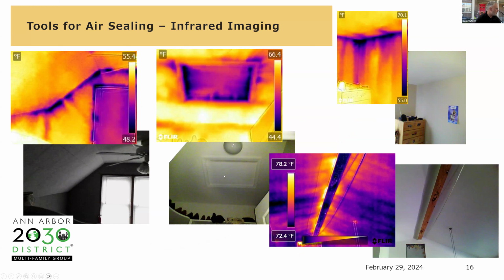We have air leakage at the attic hatch, so you can use a thin foam gasket, 3/8 of an inch, 1/4 inch gasket to seal that. Caulk. You can caulk the trim to the drywall, just make sure you go around all sides.